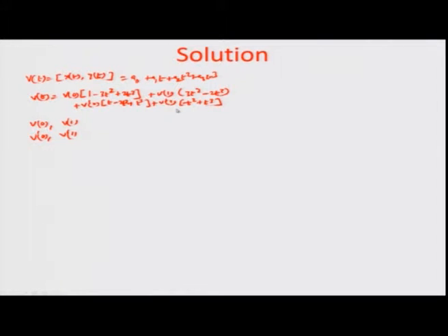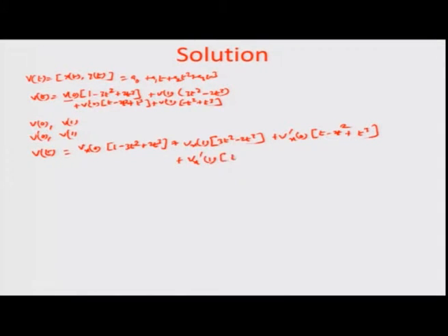And V(t) could be represented in terms of the x coordinate at v 0, that is I will call this v x 0 times (1 minus 3 t square plus twice t cube) plus again v x 1, that means at the other end extremity what is the x coordinate, times (3 t square minus twice t cube) plus again v dash x 0, that means the x slope at the initial boundary, that is corresponding to the t equal to 0 boundary, plus again the x slope at 1, that means the other boundary, that is the end boundary of the particular curve,